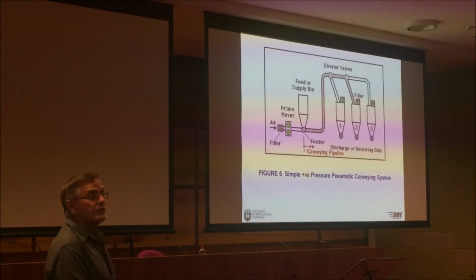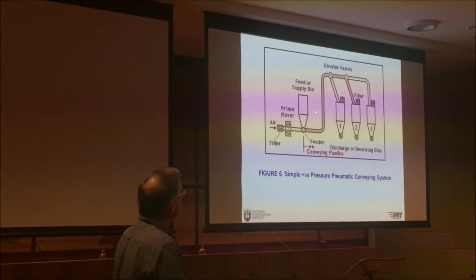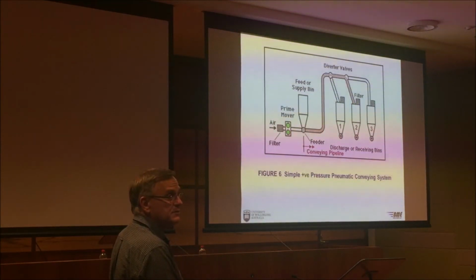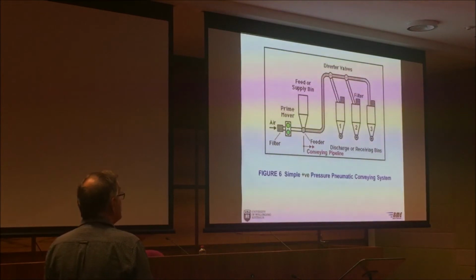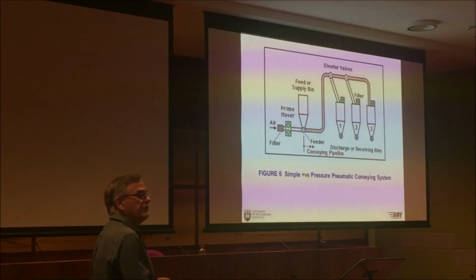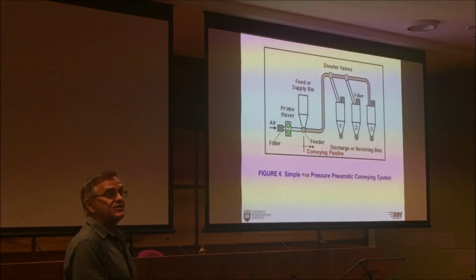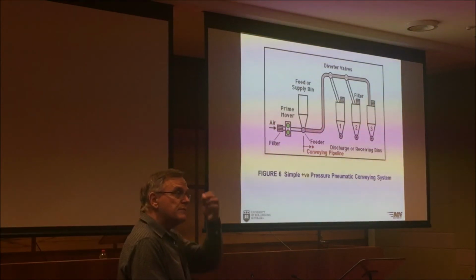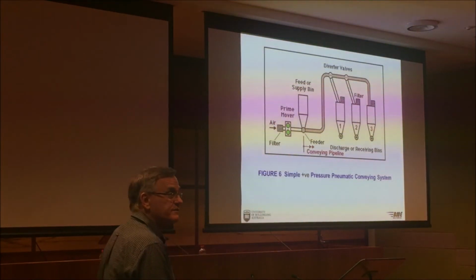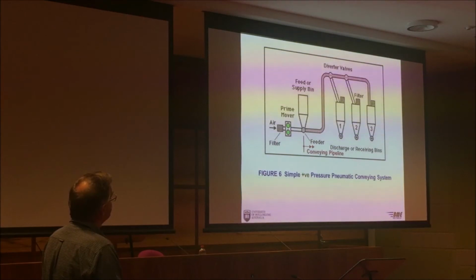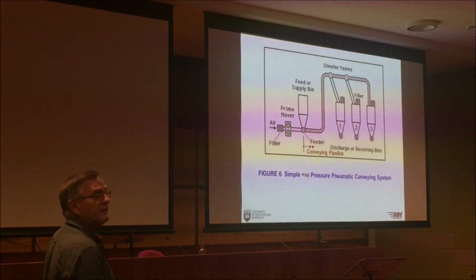When we fill up silo 1, we go across to silo 2. So we change our diverters, and that becomes the end of the conveying pipeline when we convey to silo number 2. So the conveying pipeline is getting longer. And the maximum length for design is the silo number 3. And we should always check the minimum length as well. Make sure things are still going to work nicely for us. Alright, so the conveying pipeline, you can see horizontals, verticals, bends, etc.